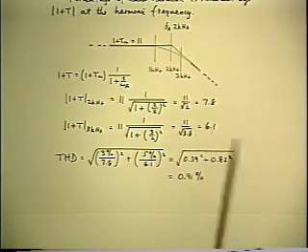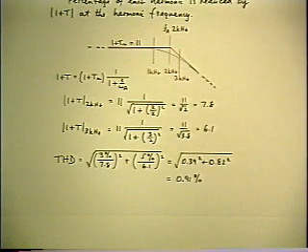So the conclusion from that, which I'm sure you know already, is that in order to make a respectable feedback amplifier, you have to keep the loop gain itself high over the entire range over which you want to get the benefit of the feedback reduction factors, which means you want to keep a high loop gain of 20 dB at least, not from 30 hertz to 2 kilohertz as it is in this example, but over the range maybe 20 hertz to 20 kilohertz.